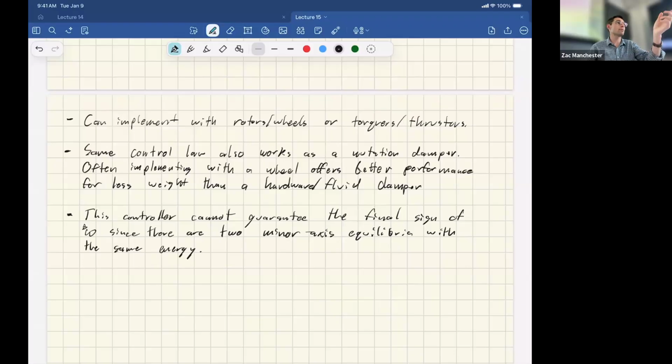If you minimize U squared, that actually corresponds to the minimum energy solution. And what that'll do is basically evenly distribute the momentum across the array. Either one is correct and either one will get you an answer. But generally speaking, the minimum L1 norm is going to basically always zero one of the wheels out, and probably that's not exactly what you want. So okay, let's write that down.